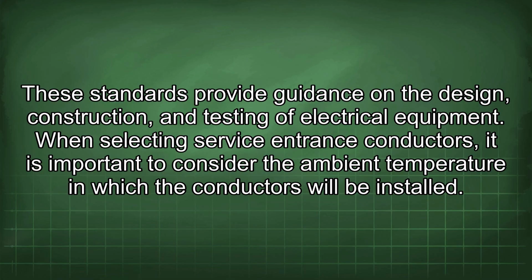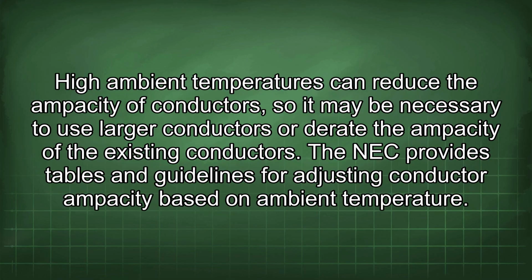When selecting service entrance conductors, it is important to consider the ambient temperature in which the conductors will be installed. High ambient temperatures can reduce the ampacity of conductors, so it may be necessary to use larger conductors or derate the ampacity of the existing conductors. The NEC provides tables and guidelines for adjusting conductor ampacity based on ambient temperature.